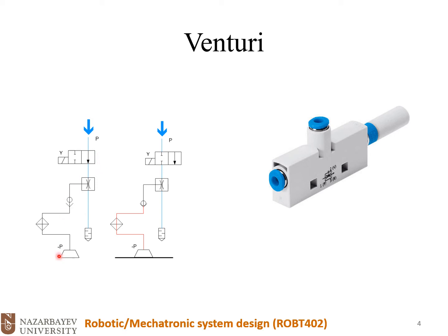So see what's happening here. We have a 2x2 directional valve. This 2x2 could be a solenoid that just opens and closes, basically opening to port 1 of the Venturi. This is port 1 of the Venturi, and this is port 3 of the Venturi. You see, this is a muffler to basically reduce the noise of exhaustion to the air.